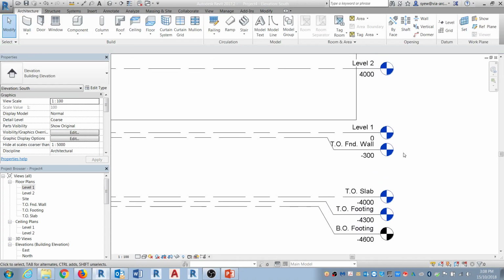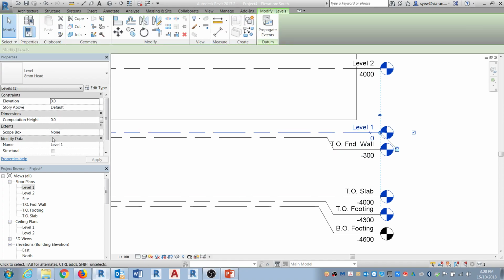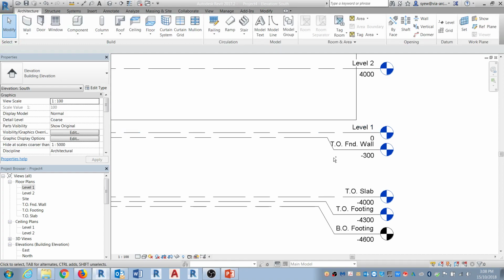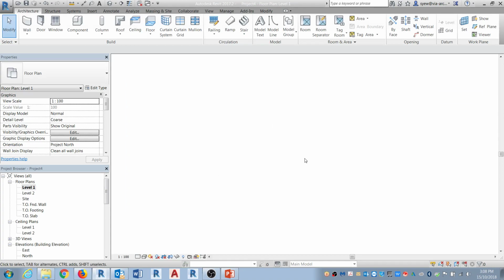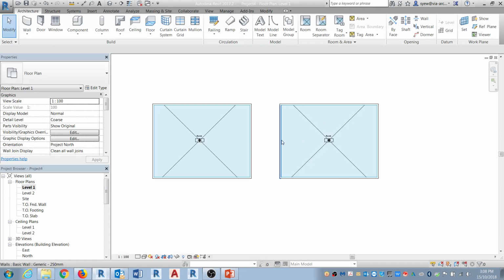So what you're going to do is go in here and define your computational height. Now, typically, I just use the same. Let's say if it's 4 feet, where you cut it, that's where I end it. Or you can say 5 feet. I typically end it at just 5 feet. Okay. Let me set that up. You notice that the room right now, if I go to this, it starts to fill in again. So this becomes very important.